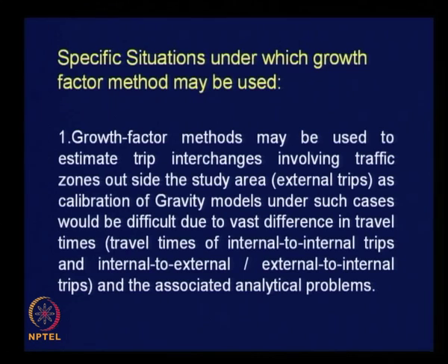Application of gravity model under such cases will be extremely difficult due to vast differences in travel times of internal to internal trips which are within a range, and internal to external or external to internal trips, and the associated analytical problems. That is how you cannot apply your gravity model to deal with internal to external and external to internal trips. That is where your growth factor methods will be very useful.